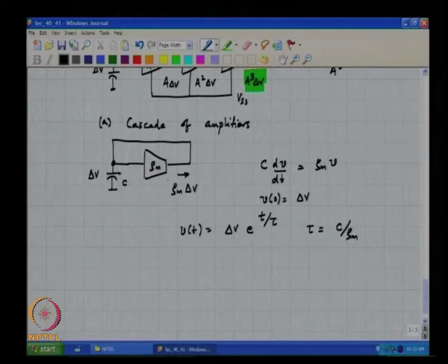Okay, so clearly there is feedback here. What kind of feedback is this? Positive feedback, because if we break the loop and come back, the response at the other end of the loop is in the same direction as the excitation. So, this is positive feedback, or often called regenerative feedback.